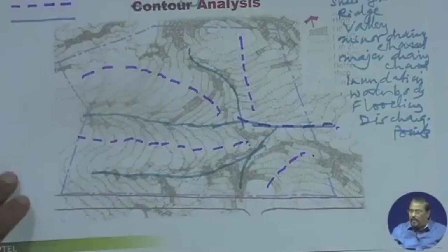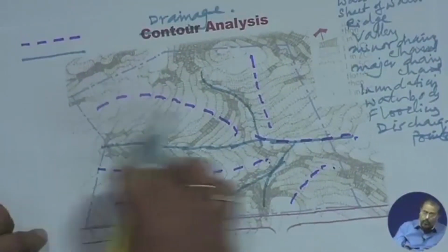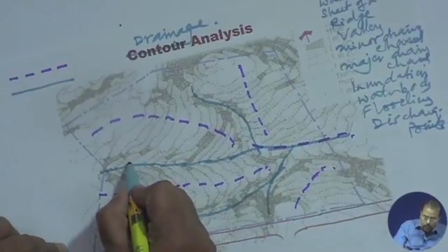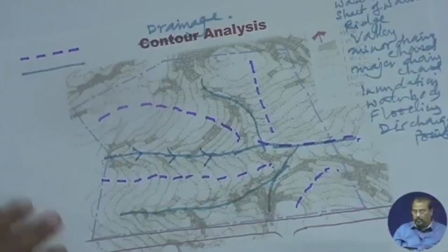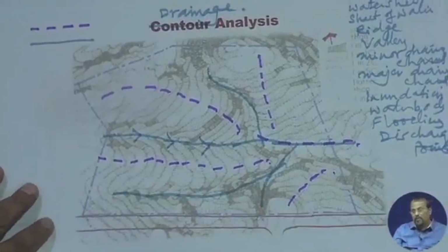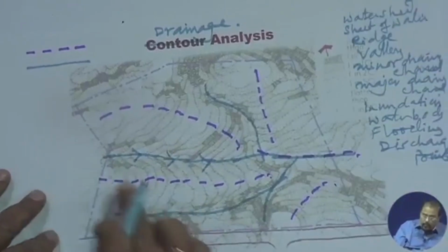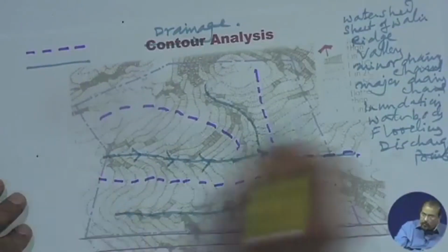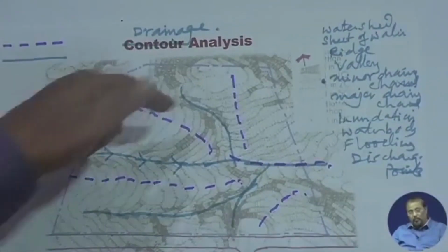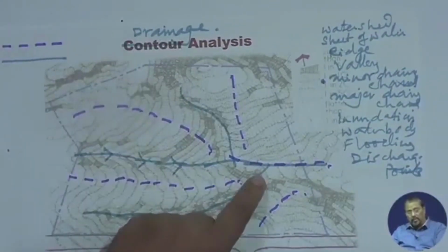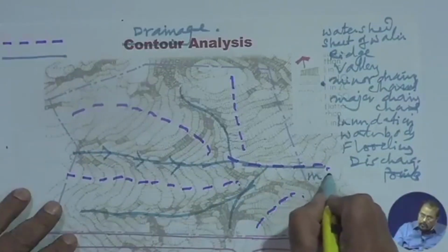So the valley becomes designated as the channels. The moment you give an arrow to the valley line, it becomes a channel, meaning a hydrological channel or drainage channel, whatever you call it. When you have many such channels, they are minor drainage channels. When multiple minor drainage channels get connected to another drainage channel, this becomes a major drainage channel.